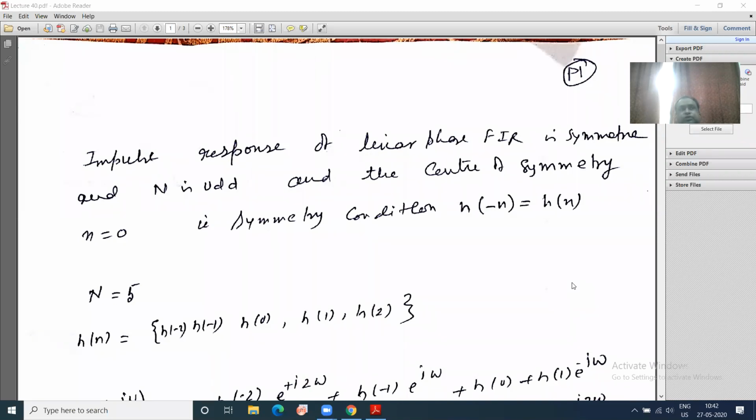So for the time domain filter coefficients, we can take the Fourier transform, DTFT, then we can get the frequency response. In other words, if some frequency response is given, then if I find the inverse transform, I can get h(n) for different values of n, and this N could be selected on the basis of the given parameter, right? On the basis of how many samples you have to design. That will be given, I have said earlier.